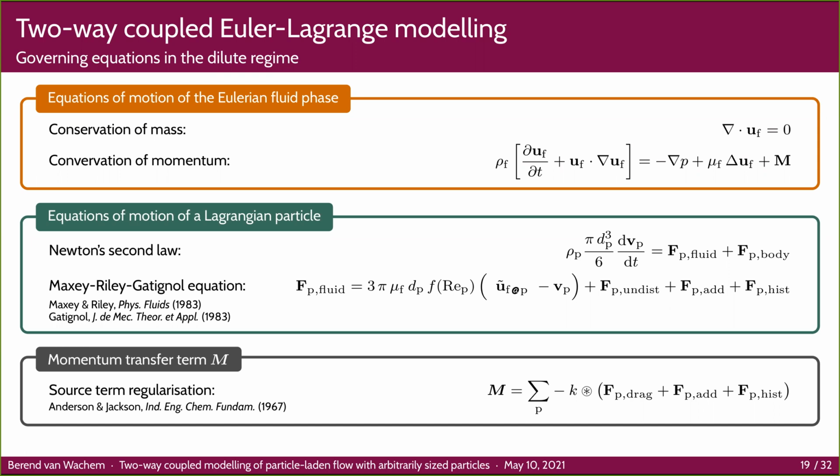Well, that's exactly the problem. So there are two competing things. You would like to have a fine fluid mesh to be able to capture the structures and details of your fluid. But up to now, there's a limit on how fine you can make that mesh, which is always said to be about 10 particle diameters. So you can't go finer. And that's always been the trade-off in Euler-Lagrange simulations. And our holy grail is that these Euler-Lagrange particle simulation methods start to approximate the accuracy of fully resolved simulations without having to pay the cost for fully resolved.